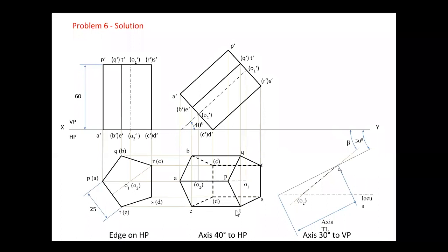This imaginary rectangle which I get here, I'm going to place on this O1 to O2. For that, I'm going to extend these two lines, measure the distance from O1 to this line and cut it down, and measure the distance from O2 to point A and cut it down.